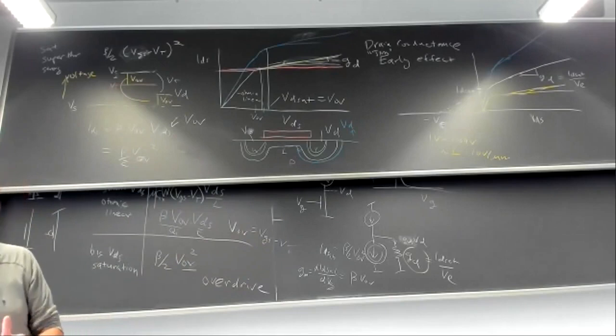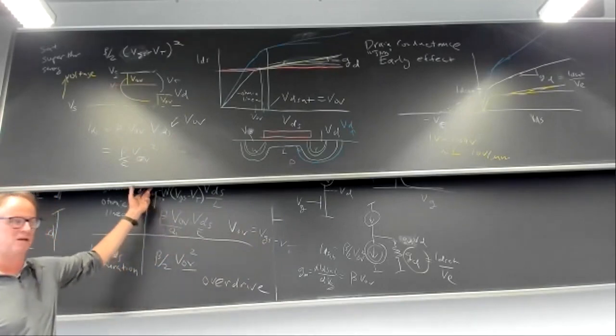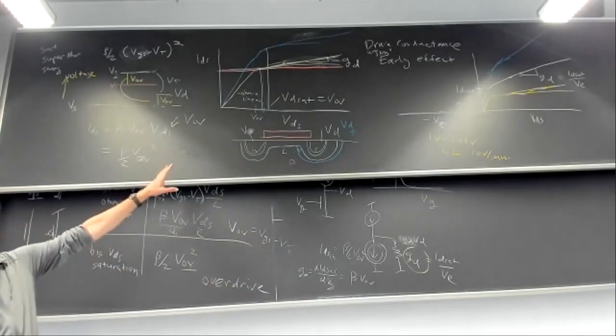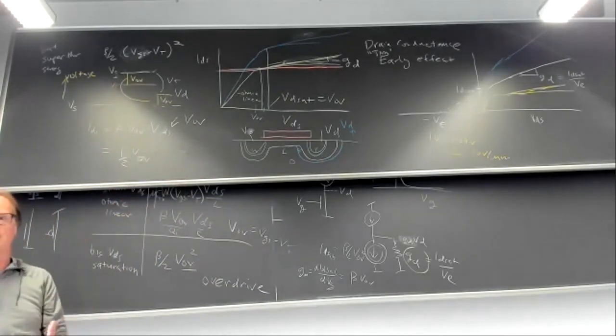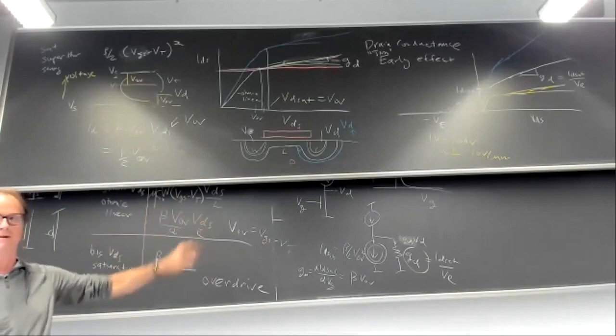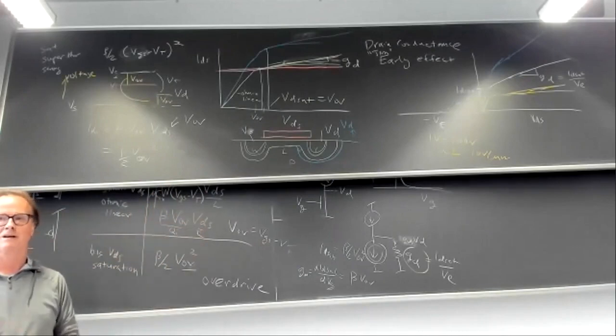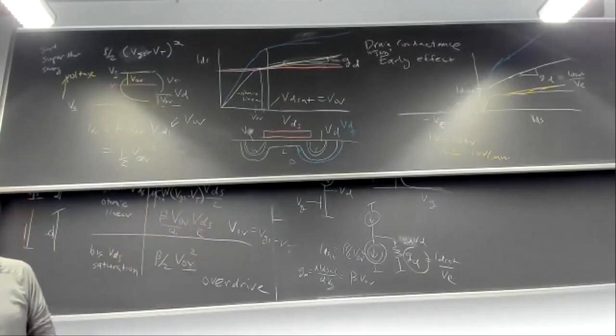That's enough for today. Plenty. Good luck with your measurements. So you're going to measure these three conditions, right? Small VDS, big VDS, and Early voltage, drain conductance. So if you manage to do all those measurements, that'll be a good step forwards.